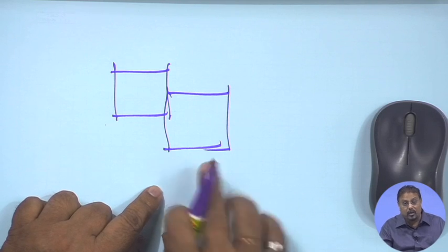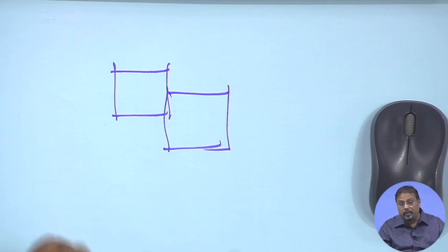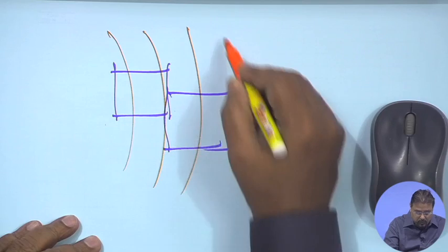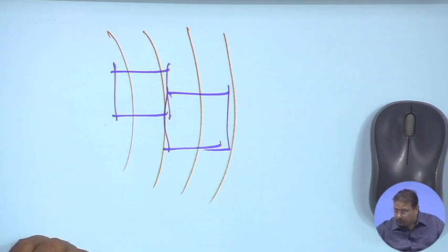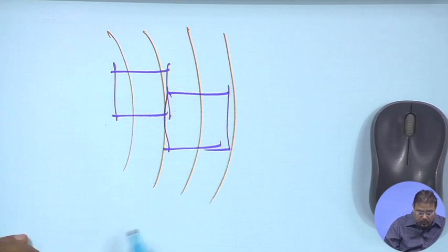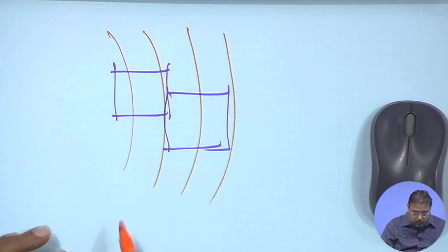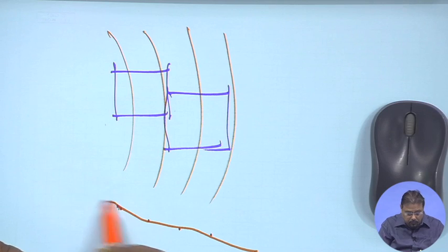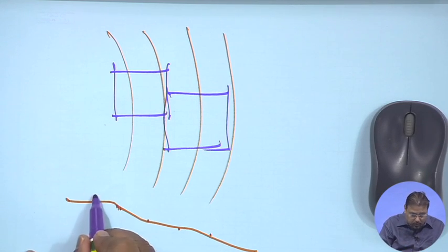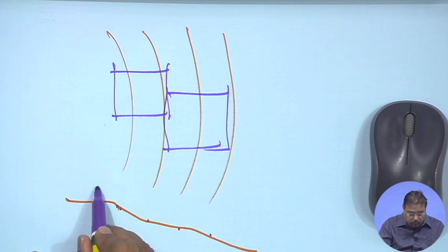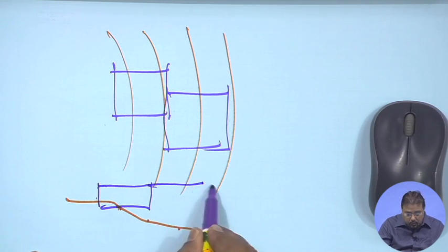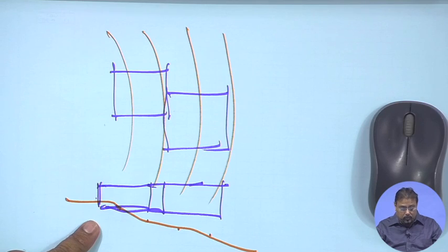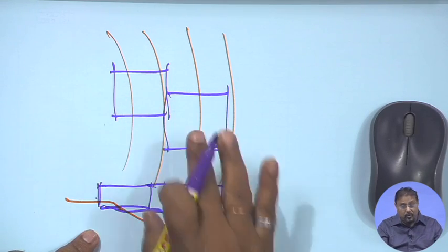One example I will give this, another example I will give you the play field, because that is the example I found my students have very clearly understood. Okay, in this, suppose you find that your contour line is going like this. Now you are deciding the spot level. In this particular contour line, if I try to draw the profile, this elevation, this is the next elevation, next elevation, next elevation. That means my site is something like this, in which the building is supposed to be placed. I am showing with respect to the building because that is best understood at this moment. Suppose the building that I have drawn over here is supposed to be something like this, but across the contour line, I will see that this particular thing which looks to be at the same level cannot be at the same level, so I lower it down.